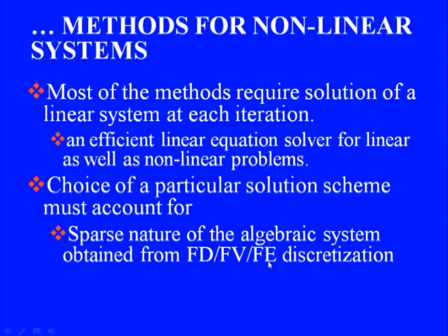With finite volume and finite element, the sparsity pattern is fairly similar. The system is never full, it is very, very sparse. So, this algorithm which we choose for the solution of this system must account for this sparsity. It should not require more storage than what is absolutely needed for our sparse system.